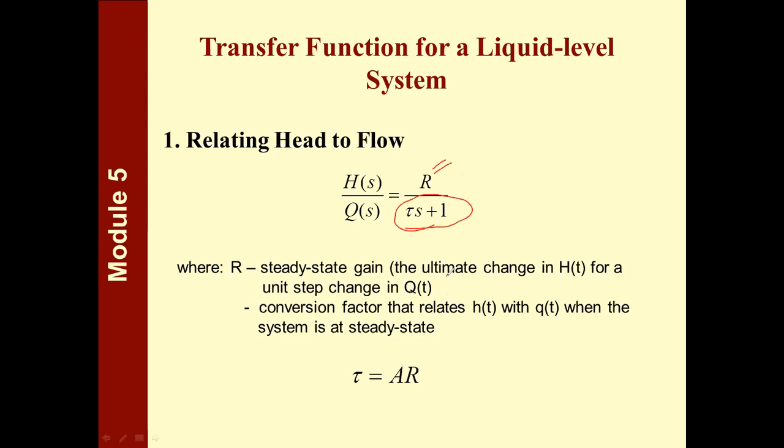So nonetheless, whether we speak of head to flow relationship or temperature to temperature relationship in the case of the thermometer, your steady state gain always is the ultimate change in your output, whatever that output may be, for a unit step change in the input. Okay, so take note of that.